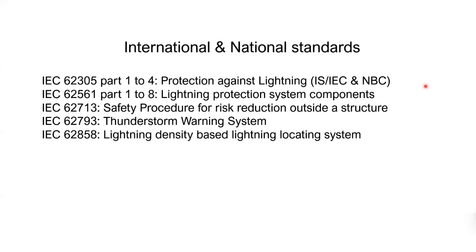The energy consists of heavy specific energy and charges, and the effect of lightning is not only a current flow. It can heat material, it can produce large flashovers, and temperature rise, not only at the point of strike of the lightning. If you have a loose contact, almost 30,000 degrees of temperature may be produced in a loose joint. So lightning is not like other subjects of electrical engineering. Lightning protection is a very special and very specific subject.